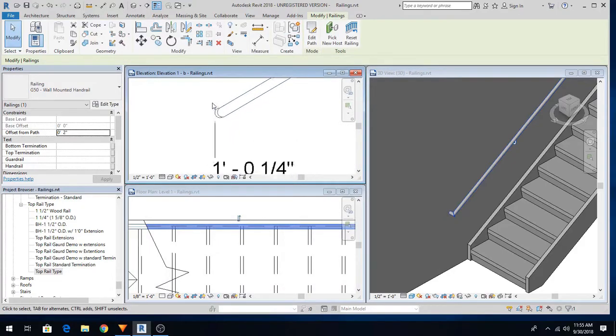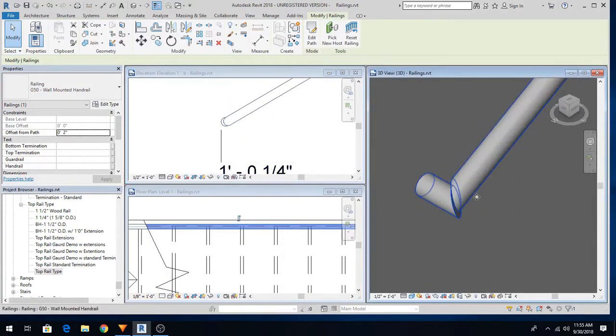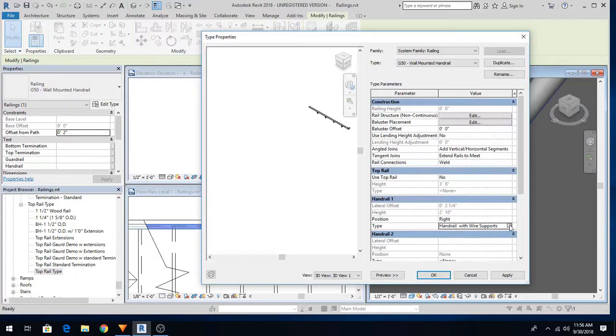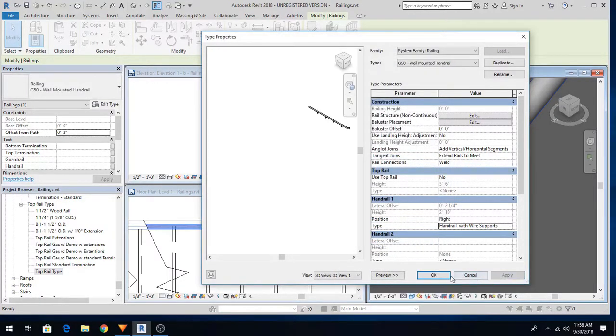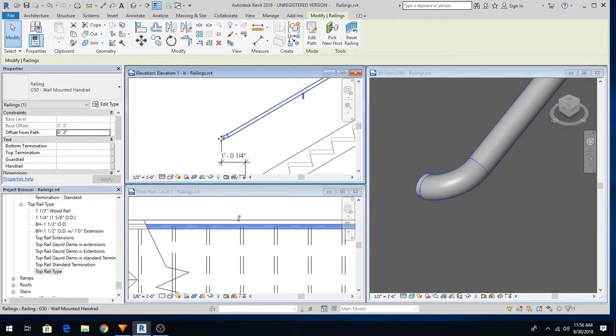Now we have our extension as shown, although it's not the prettiest in the 3D views. So sometimes a fillet will help that. If you come to fillet, let's make it a 2-inch fillet. Okay, and that cleans it up a little bit there.